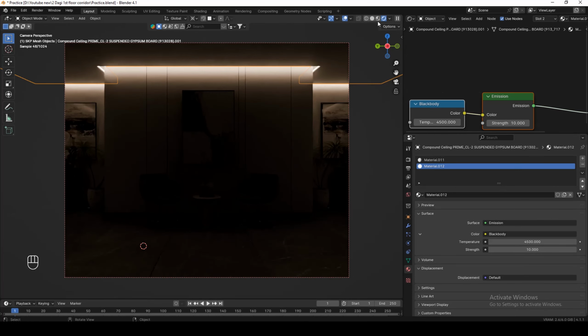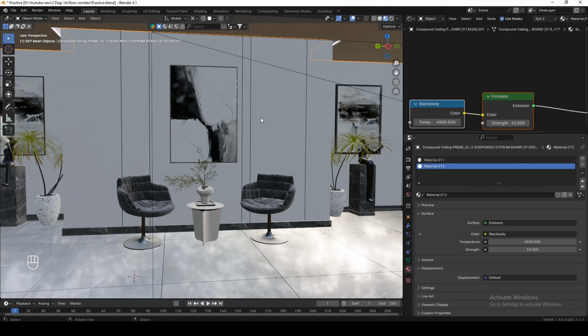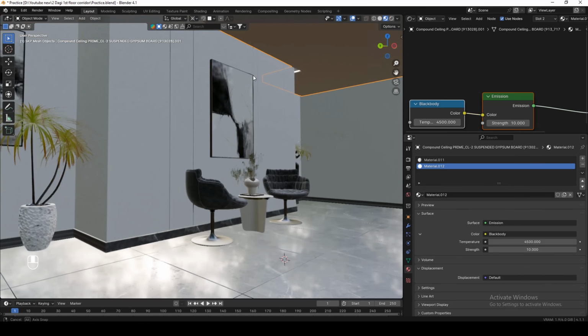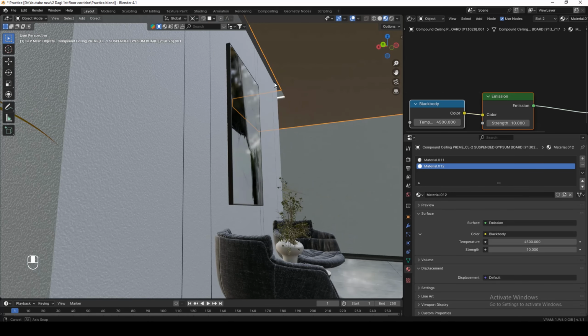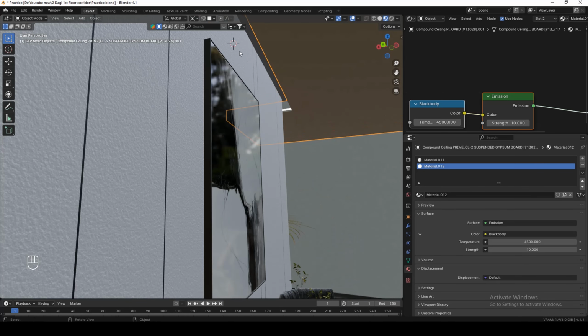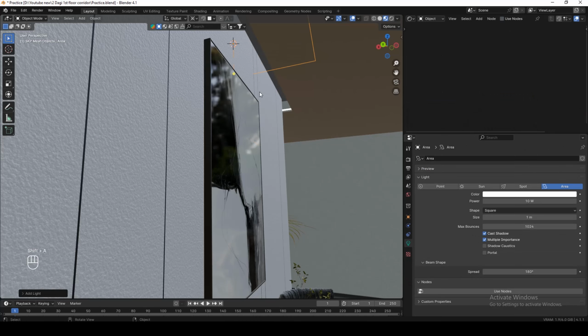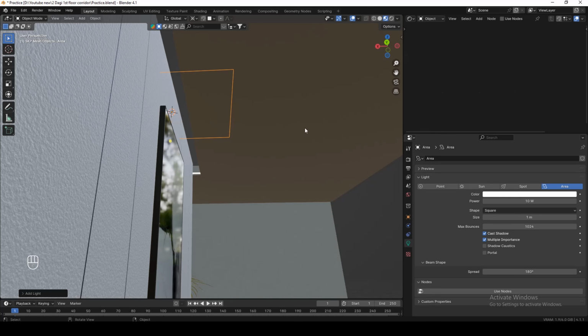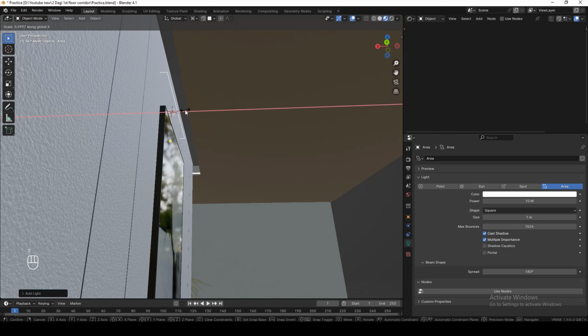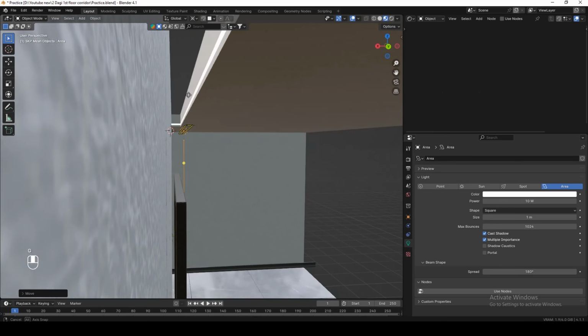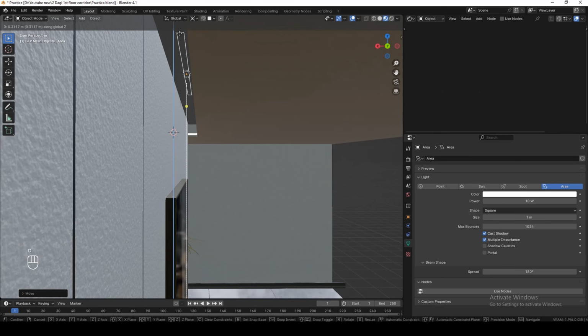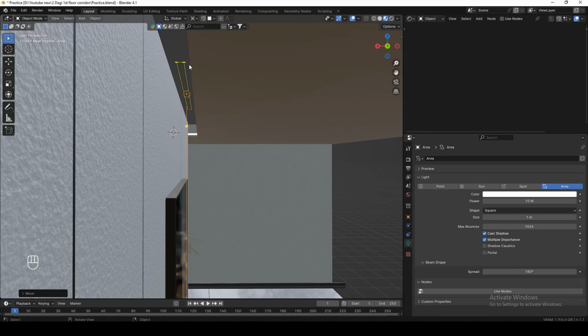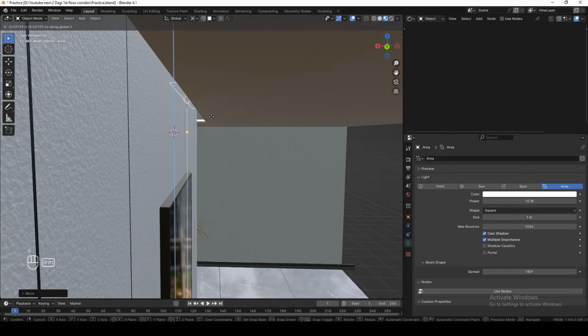After this, let me go to this EV material preview, and let me add in some lights. I'm going to add some light right here. I'm going to click right here, press Shift A, and then add an area light like this. I think this will be good. Then press S and then X to scale it on the X axis, and then press GX. I think this will be good, and then press GZ. Just move it right around here.